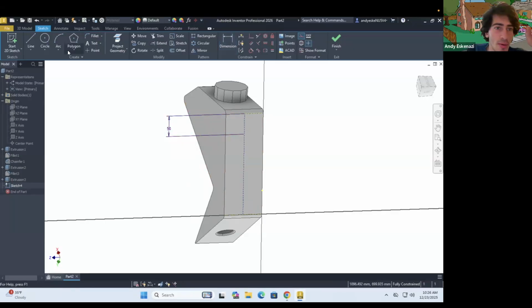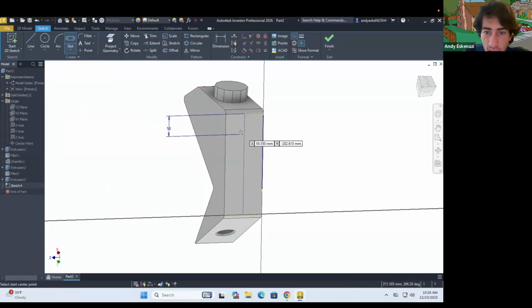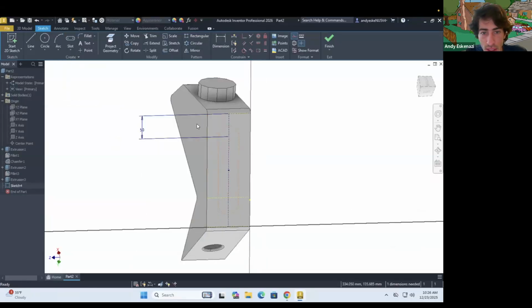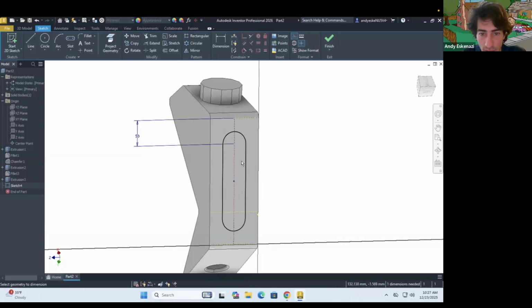The reason why I'm saying this is because now we go here to our friend polygon. I'll click on that slot right there, and I can now do that slot, which is divided by 2 points. So again, I forgot to unclick that area right there. So what I'm gonna do is select those guys. Well, actually that line, I wanted as construction, very good. There we go. Now what I need to do is define with letter D that distance and make that 20. Voila, that is good.